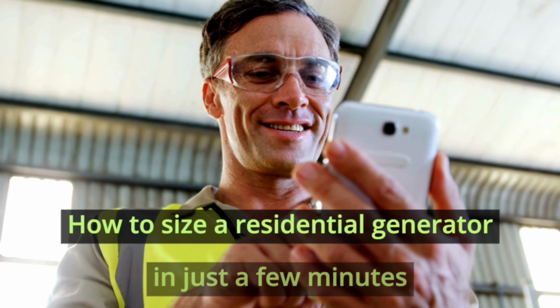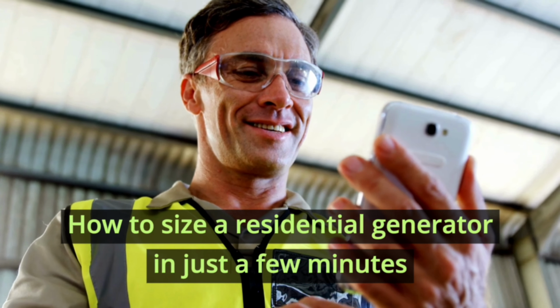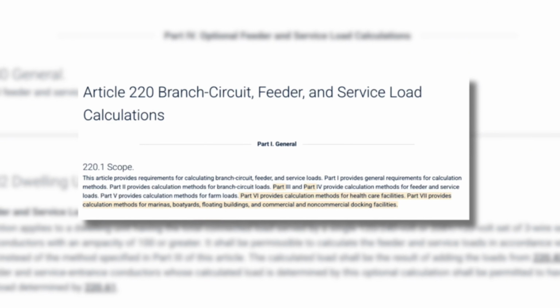In this video, we'll show you how to size a residential generator in just a few minutes using our load calculator. The tool follows NEC Article 220, so you'll get a clear, defensible load calculation that will result in better generator sizing with fewer callbacks and smoother approvals from inspectors and utilities. A professional generator size estimate is also helpful in a lot of other scenarios. Because it's so quick, you can add it onto any load calc that you're doing to provide more value to your customer and help drive sales down the line.